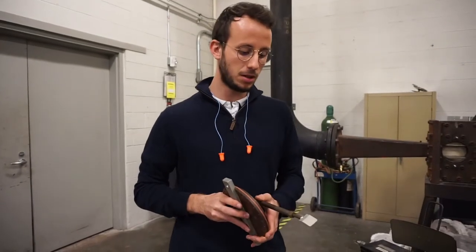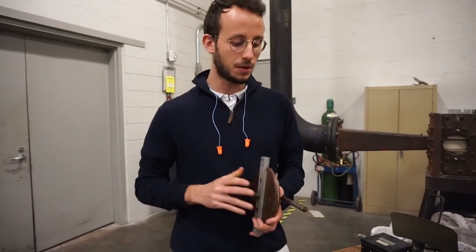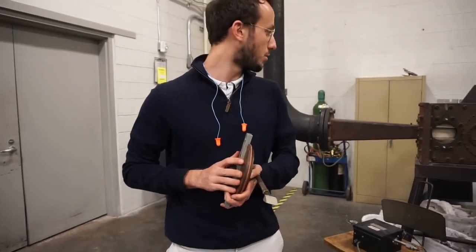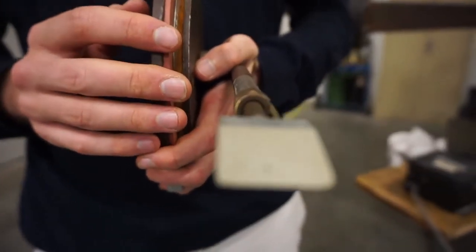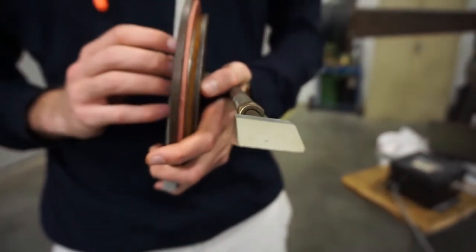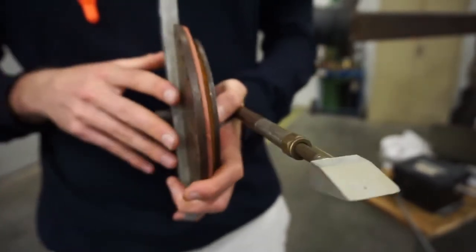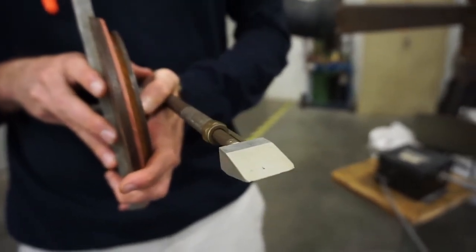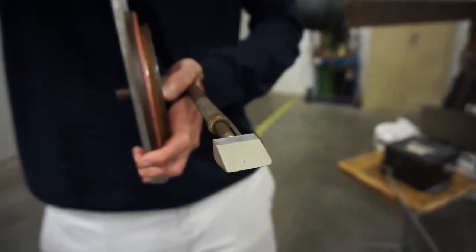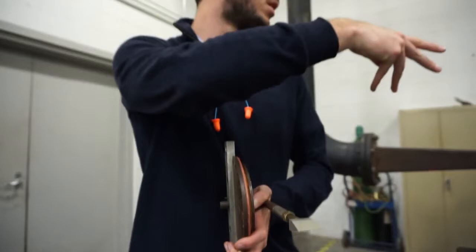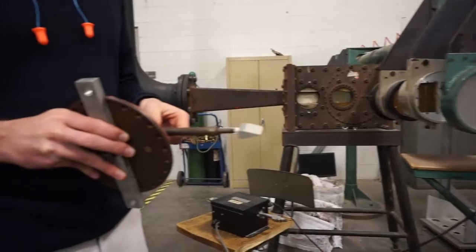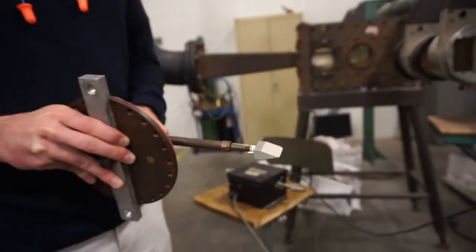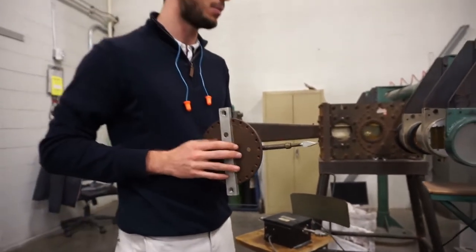The last part of the blowdown tunnel consists of putting this wedge into the blowdown tunnel. When you put this wedge into a supersonic flow, you will see an oblique shock that will be created over there, and we'll be able to see this oblique shock on the screen of the Schlieren setup. We'll also be able to record the static pressure due to this static tap on the voltmeter, like we did for the pitot probe and the static tap before.